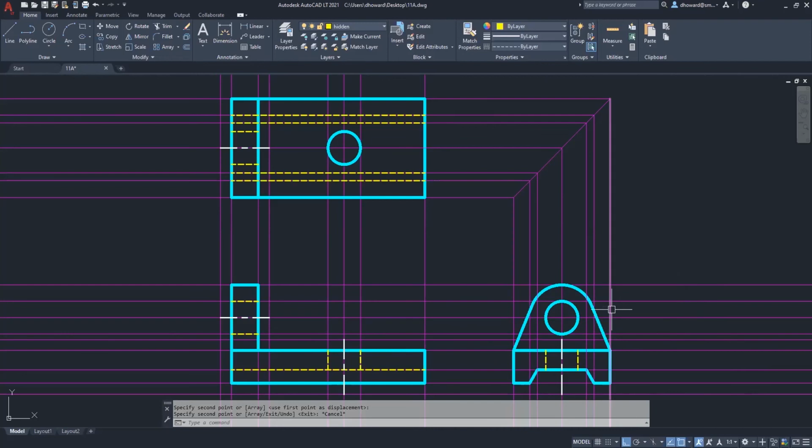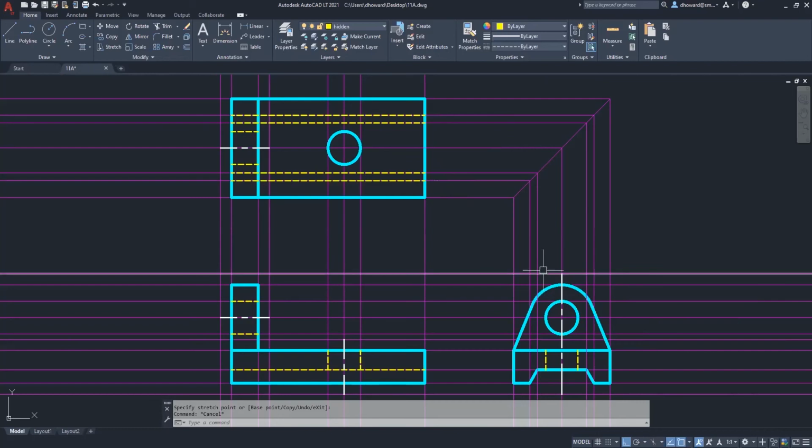And I need to put the center line in here. I'm just going to extend this one up. How far up? I need to offset this guy 1/4 of an inch, so I have something to click on. I'm going to do the same on these. You know, I'm going to show you a trick. Let me get to that one in a minute. So I've extended this construction line up 1/4 of an inch, offset it 1/4 of an inch, so I have something to click on for that center line. And then I'm going to do this.